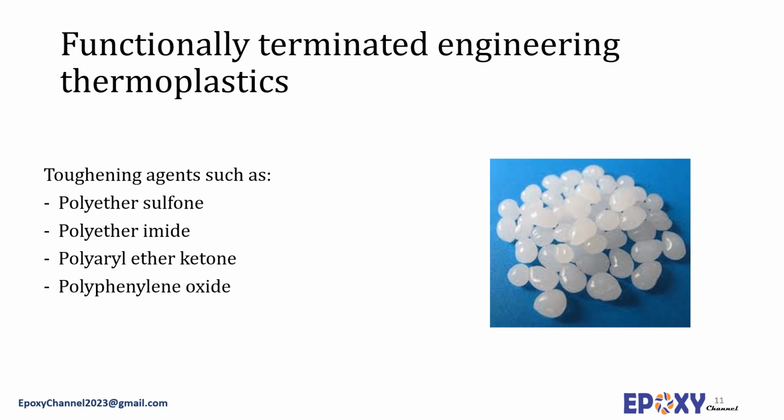The thermoplastic resins are usually blended with the epoxy resins in a solvent solution. It was necessary to increase the compatibility and interfacial adhesion of the thermoplastic modifier and the epoxy resins. The problem of poor miscibility of the thermoplastic resins and poor processability of the final products are the main reasons that these materials have not achieved commercial success yet. The thermoplastic additives offer comparably better high temperature performance, but they are more difficult to formulate. As a result, the cost of these adhesives is generally much higher than that of other toughened epoxy mechanisms.